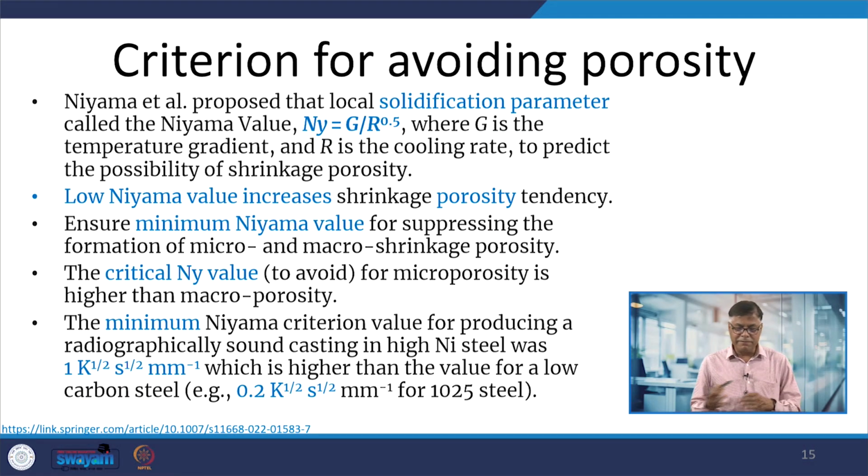So, efforts have been made by multiple researchers to find out what conditions promote this kind of porosity. Niyama and ETL proposed a local solidification parameter, which they termed the Niyama value, Ny. They suggested there has to be a particular value of this parameter, which is the ratio of G by the square root of R, where G is the temperature gradient and R is the cooling rate.